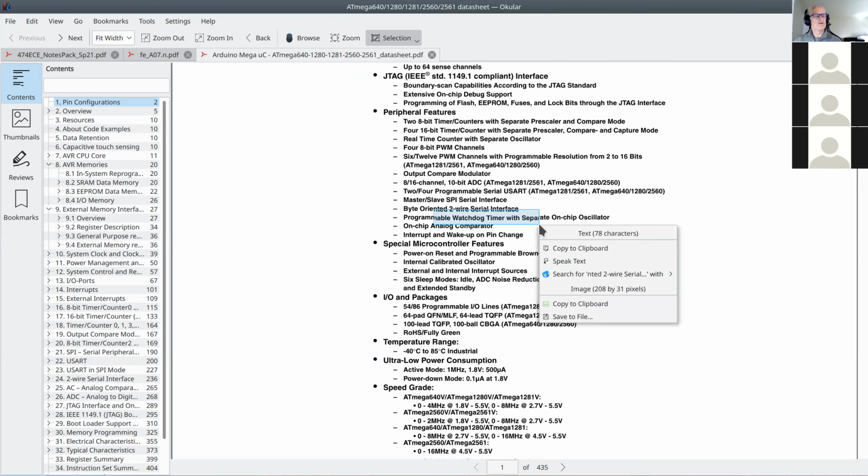Watchdog timer, we're probably not going to use, but that's a very common thing in embedded systems that everyone should know about. What it is: we all know that occasionally a computer can have a software bug that causes it to lock and hang. On your PC, if it crashes, you restart it, and that's okay. But what if your embedded system is just controlling a refrigerator or something? Well, you don't want the consumer to say, "Oh, my food smells bad. I need to reset the refrigerator."